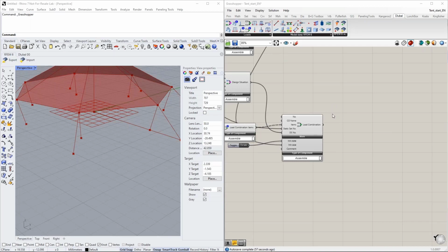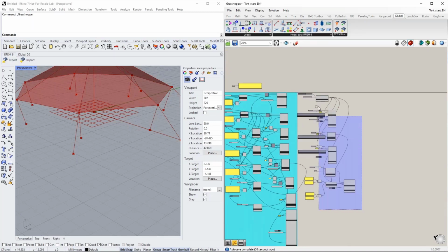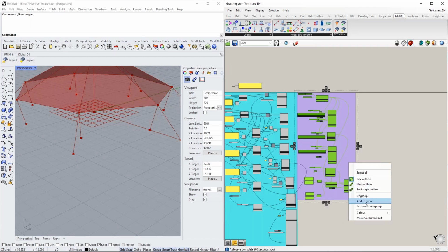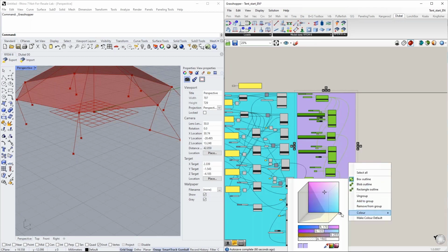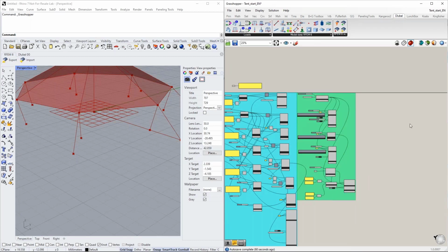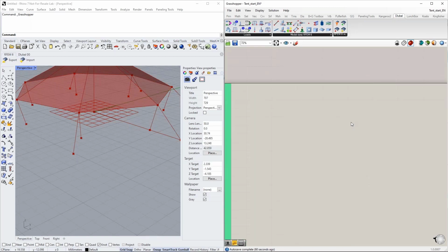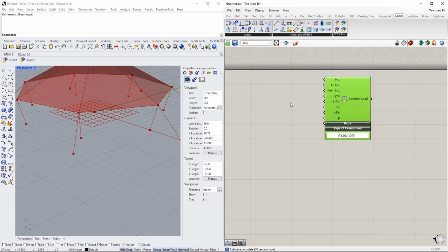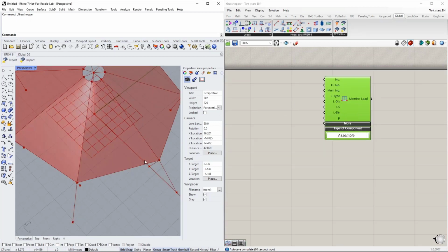Now the last topic is the loading topic. Let me quickly group this one as well, with any other color, green. And the last topic here will be the loads. Again, just 3 loads so that you see how it can be used. My first load is a member load. I want to define the sag of my cables. The cables are limiting my membranes here.